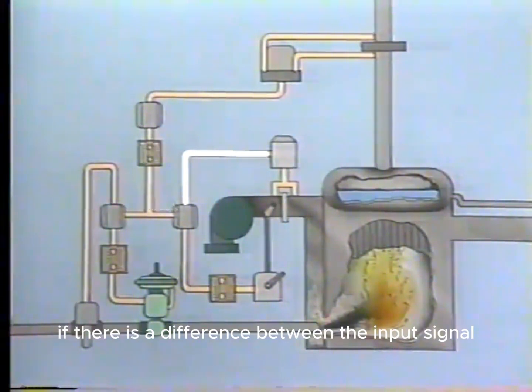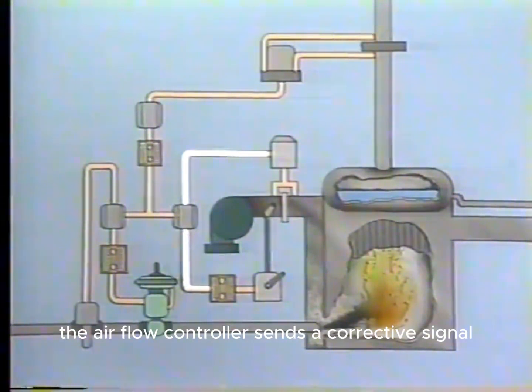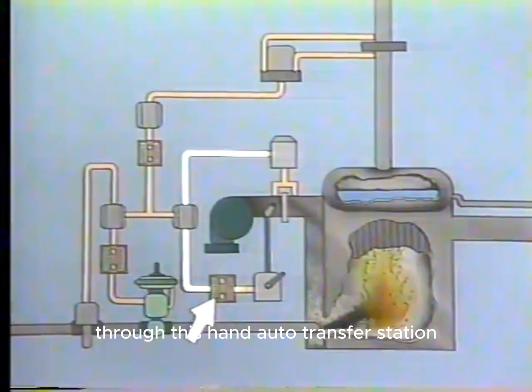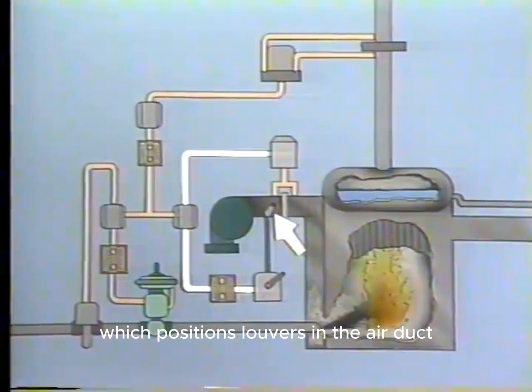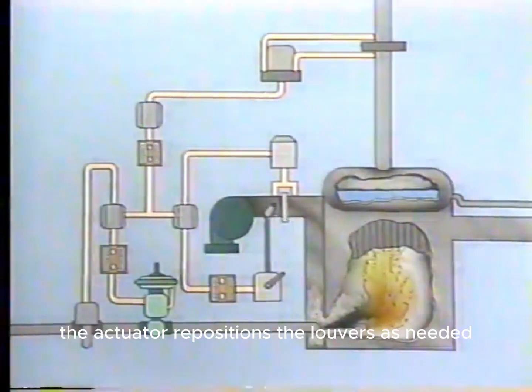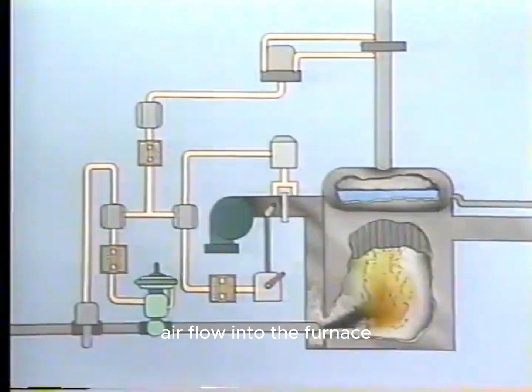The airflow controller compares the signal to the set point. If there is a difference between the input signal and set point, the airflow controller sends a corrective signal through this hand auto transfer station to the actuator, which positions louvers in the air duct. The actuator repositions the louvers as needed to allow either more or less airflow into the furnace.